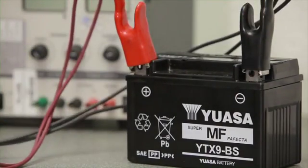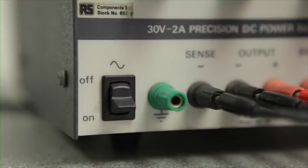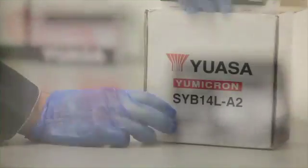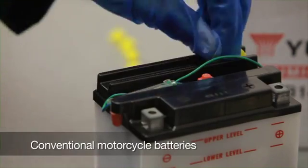Failure to follow the proper activation procedures not only leads to premature battery failure, but also voids the warranty. As the procedures used to charge each type of battery are different, always check which type of battery you're dealing with before you begin. To charge a conventional battery, place it on a level surface, then remove the filler caps, placing them safely to one side.